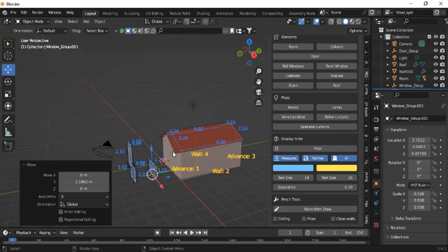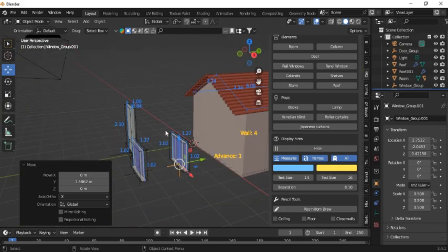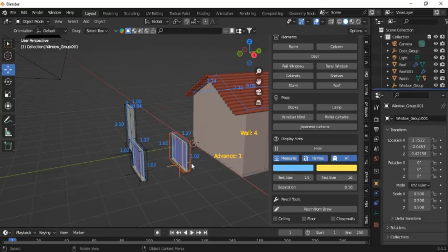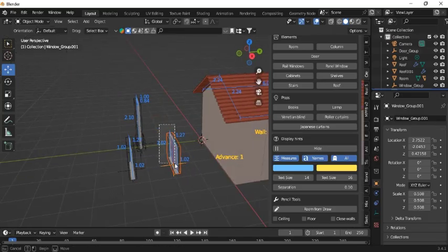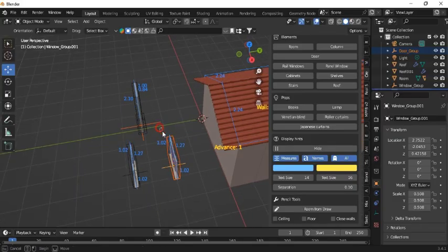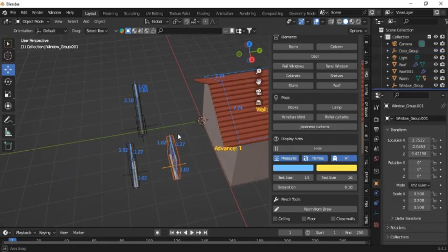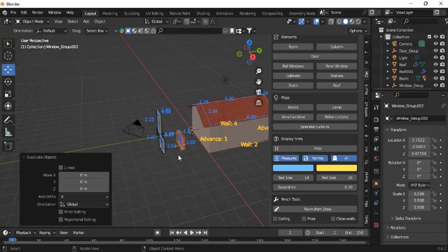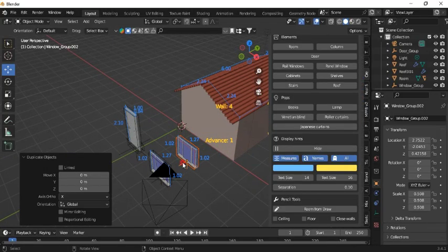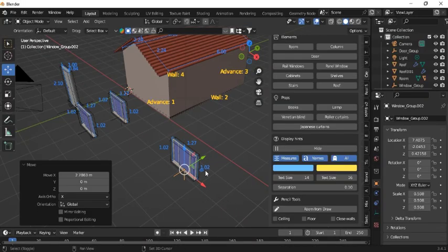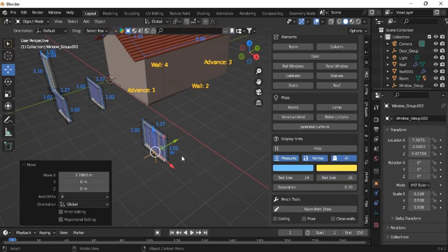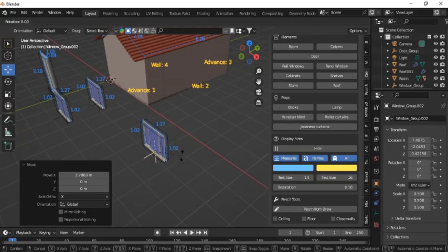So just come in here and select this again. Just click and drag over it to select it like this. Shift D to duplicate again. Select this and move this out like this. I'll press R, press Z, press 90 degrees.